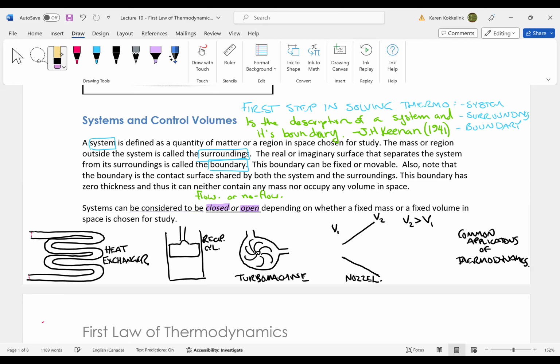I could have closed it over here, but I decided to close it at the end. Of course, my calculations depend on where I closed it, but my calculations all start with the definition of that boundary. I'm going to include all the volume inside this tube as part of my system. If it's called my system, then it's inside my boundaries. So I better draw a boundary around all the fluid that's inside this tube.